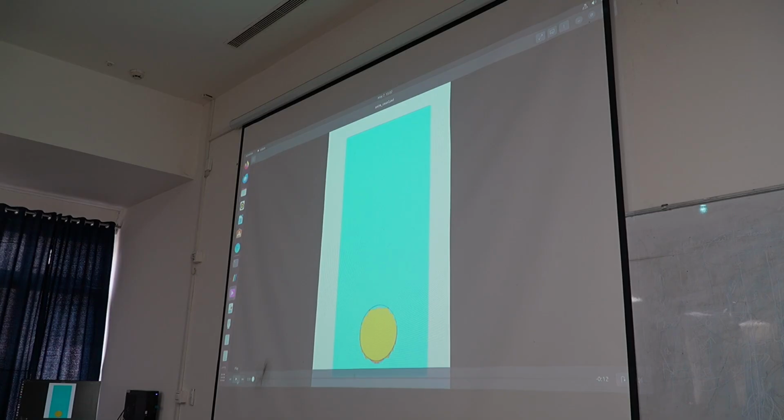Once we get the centroid, it is recommendable to use central difference or backward difference for calculating the velocity. It is better to go for central difference because the order will be higher, meaning the order of accuracy will be higher and the error will be less.